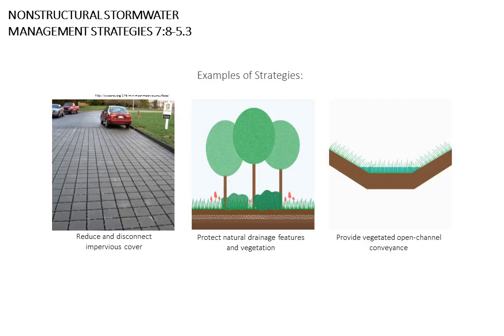A deed restriction or other department-approved restriction is required for all non-structural stormwater management measures to ensure that they are preserved and maintained. For a more in-depth discussion of the non-structural strategies, as well as examples of low-impact development calculations, please see Chapter 2 of the New Jersey Stormwater Best Management Practices Manual. For information on which BMPs provide non-structural benefits, please see Chapter 9 of the New Jersey BMP Manual, in which each BMP with a leaf icon on the title page is able to assist with certain strategies.